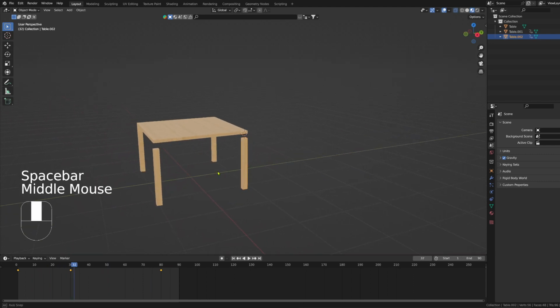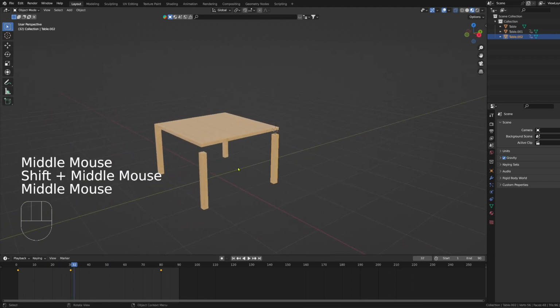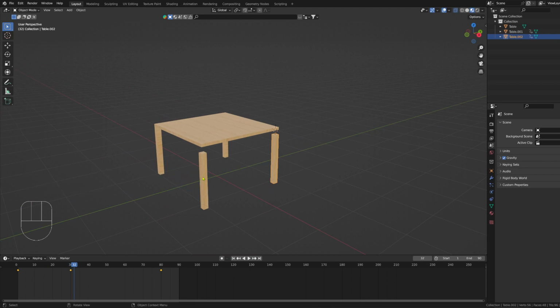Okay, so that is another basic animation, but now it's with individual origins, as well as learning how to separate meshes into different objects and moving origins using moving the origin to geometry, or moving the 3D cursor to where you want, and then moving the origin to 3D cursor.